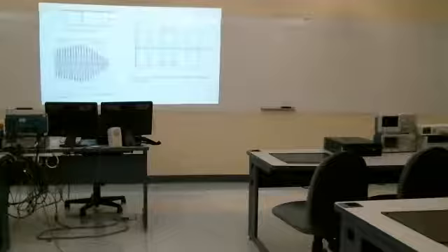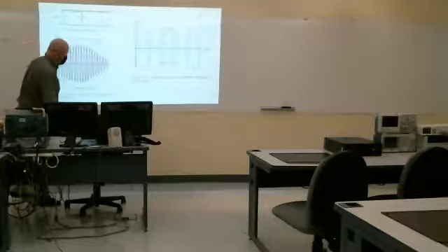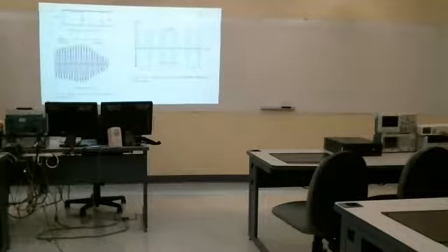And then this is the new component that's present in AM radio that's not present in double sideband. But this is nothing more than, it's a sinusoid in time. It's just an impulse in frequency. So I won't write down the formula for the spectrum, but it would be just our double sideband spectrum, which we had last time, plus a pair of impulses.